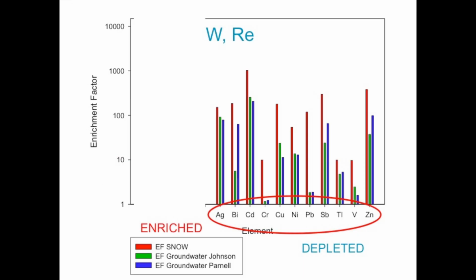The other thing I wanted to mention here, so we've measured a long list of trace elements. With the ICP-MS we can measure more or less everything we're interested in. And all of these trace metals that are listed here are all being filtered out by the soil. It's not that the soil's filtering out the lead, it's filtering out all of the things that you see listed here. And I think that's fascinating. The soil is doing really a remarkable job.